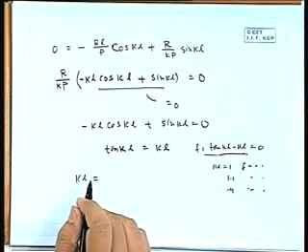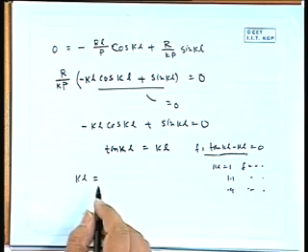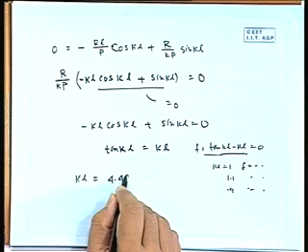So like that, you just calculate, substituting some values of kl. So tan kl minus kl should be equal to 0. So kl you can start from say 1, then 0.9, 1.1 or 1.5, 0.5. So initially you can go with a large interval. After that it will give some neighborhood. So within that we have to refine, and we will get the value of kl. That should be equal to 4.49.